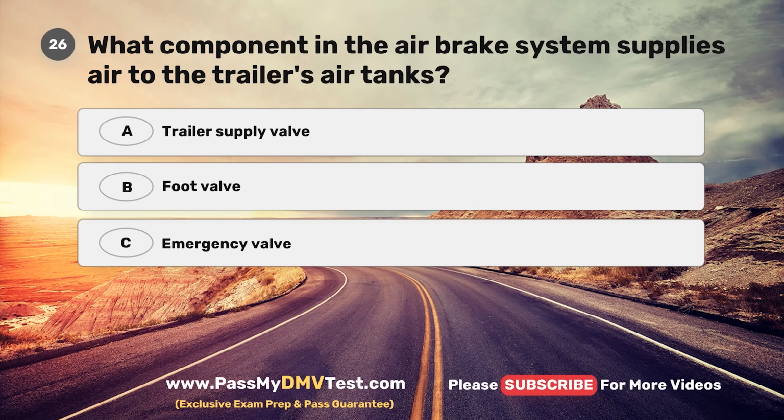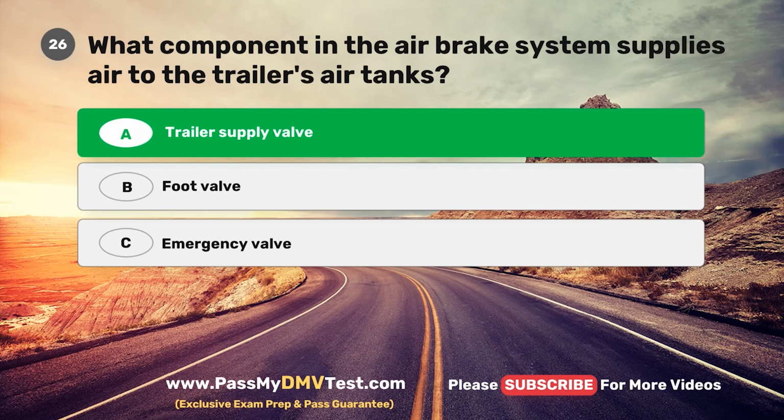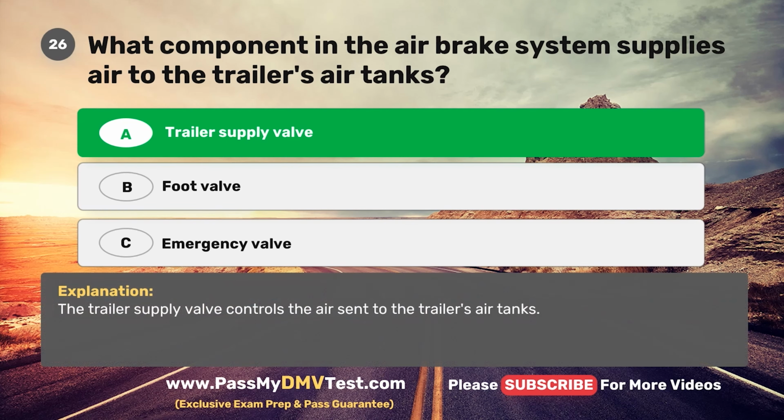Question 26. What component in the air brake system supplies air to the trailer's air tanks? A. Trailer supply valve. B. Foot valve. C. Emergency valve. The correct answer is A. Trailer supply valve. The trailer supply valve controls the air sent to the trailer's air tanks.